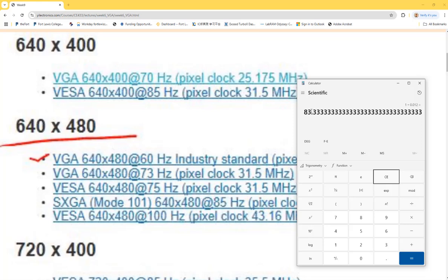It's because 640 by 480 is the pixels of the picture, but the VGA standard protocol for this 640 by 480 standard requires some redundant time to be spent in order to have a very stable picture assignment or solid colors. So these are not pixels, but these are time.